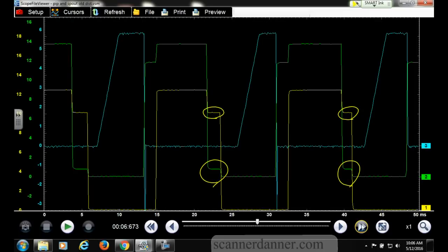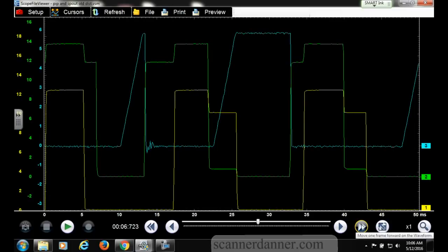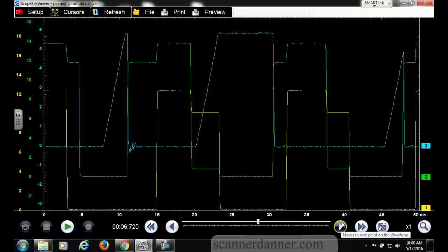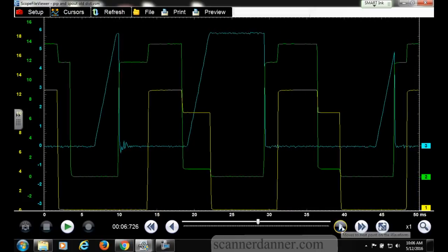I'll maybe try to dig some of that old information up. These pictures were taken, Kendall, when we raised the RPM a little bit, because that's when our misfire was most pronounced, and that's when we see my fat pulse coming up, and my little tiny pulse right there.